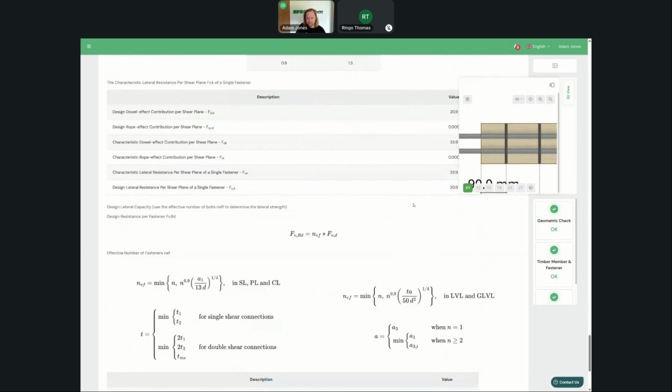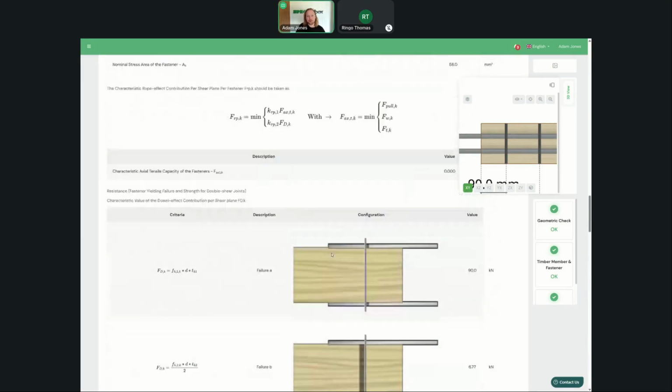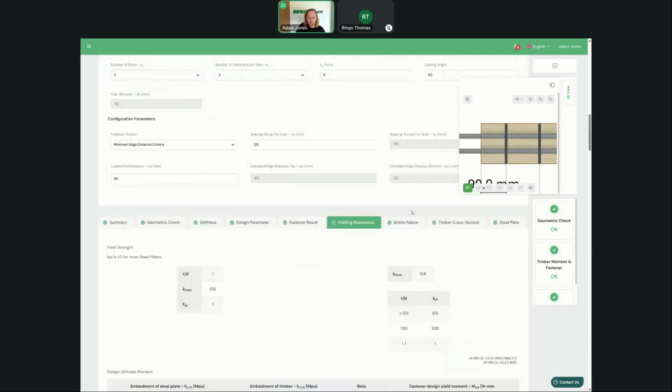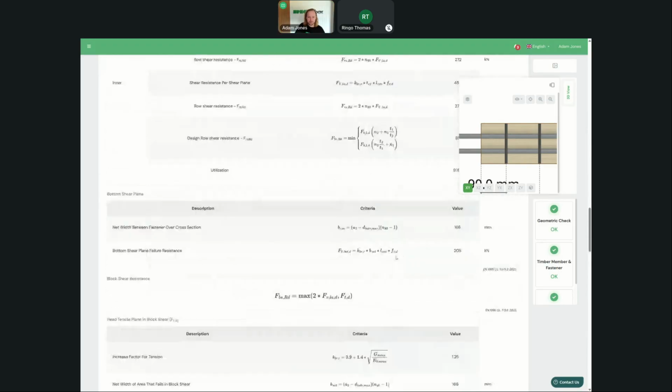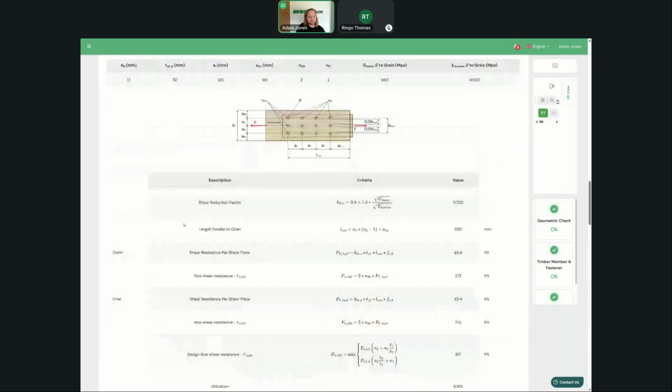And then that's calculated in a similar way. So with that, you get extra capacity there. That's for the yielding equations where you get help. But as we were failing before in brittle failure mode as well, we're spreading the load a little bit better, and we've now got it down to 45%. So that was one way of optimizing.